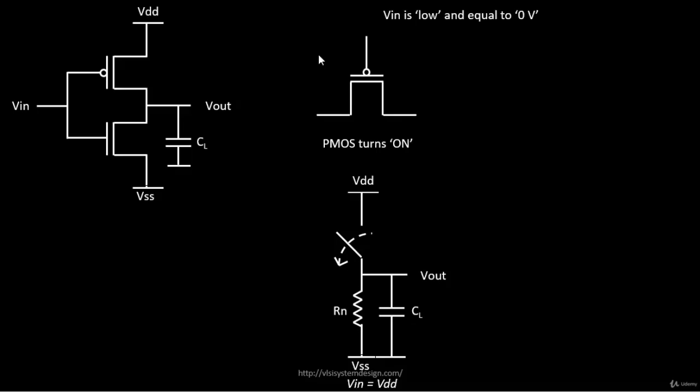For a MOSFET, everything becomes the same. Just because of the polarities of PMOS and NMOS voltages, the condition arrives to be something like this: negative VGS should be less than negative VT for a PMOS to be turned on. In the case of an NMOS, positive VGS should be greater than positive VT for it to turn on, which was the case in the previous boundary condition.